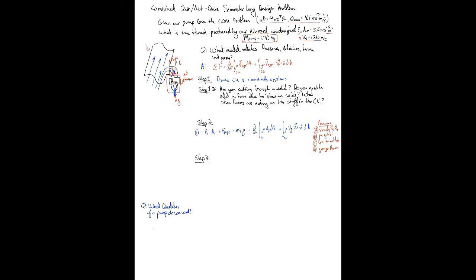So because of steady state A, this is 0. And because we've assumed uniform flow and rho is equal to a constant, this becomes a summation. Our second integral becomes a summation of all the entrances and exits. So let's simplify and solve. Step 3. Simplify and solve, and in this case the thing we're solving for, which is F pipe, is equal to